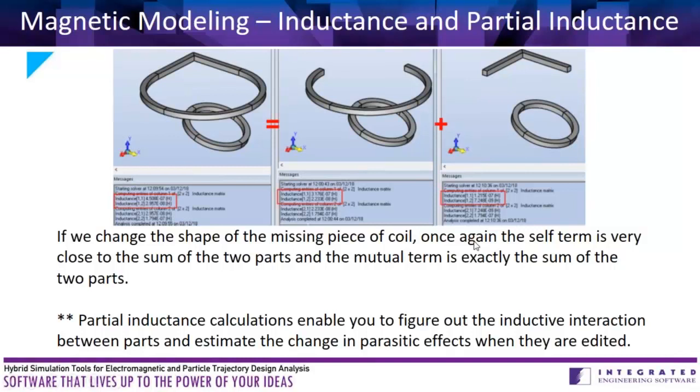So again, if you get an inductance that's big enough for the frequencies and voltages and so on that you're working with, then you might want to draw that mutual term right into your circuit diagram for modeling purposes, to model in your circuit simulator what's going to happen.